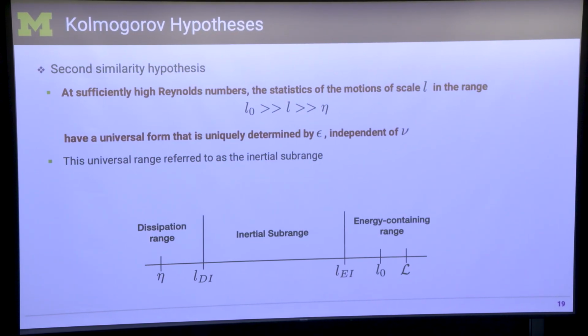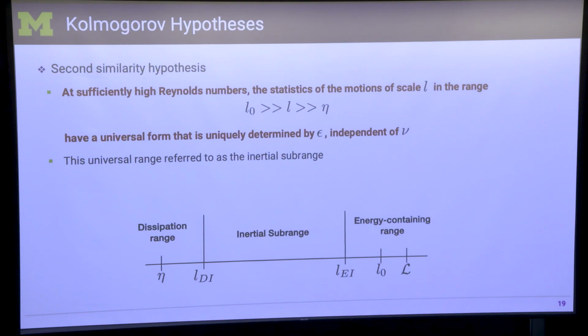There's only one other term that you have to know, which is what is called the inertial range. So you have the large eddies, and they're unstable, they're going to break down. Your viscosity is sitting at the other end. Think of it like just eating all the eddies coming. This is insatiable. It just takes every eddy of small size, eats it, and destroys it. So between these two extremes sits the middle part, whose only role is to transfer the eddies from the large to the mouth of viscosity. Right? So that's the part in the middle. And so that's the inertial range for turbulence.